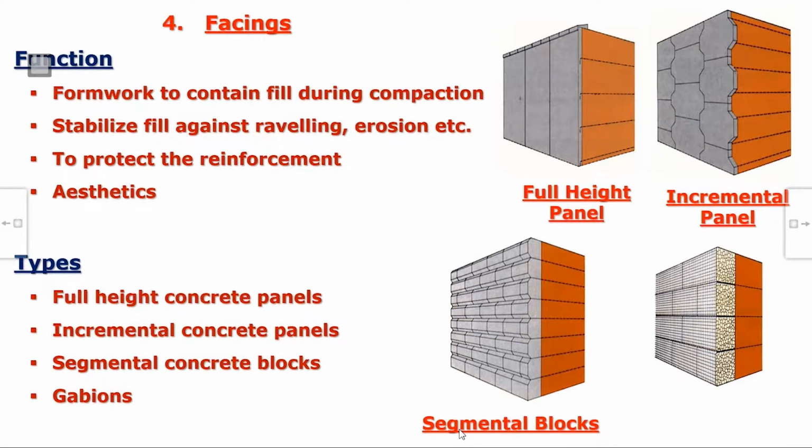Another thing which is used is gabions. These gravel or cobble filled gabions, wire netting structures, you use them and you physically interlock your reinforcement here. Advantage of gabion is, number one, gabion acts as a drain also. We need a drain behind the fascia, so there, if you use it imaginatively, you can use gabion as a drain also.